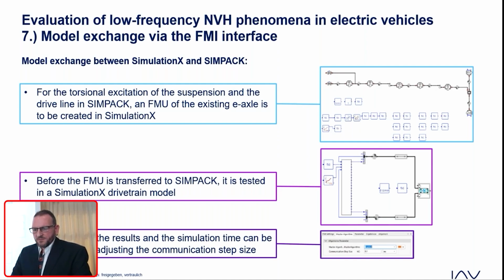Before the FMU is transferred to SimPack, it is tested in a SimulationX drivetrain model. The quality of results and the simulation time can be influenced by adjusting the communication step size of the FMU, as you see here. After the integration of the FMU in a SimPack model, the functionality and quality of the results are evaluated as very good.